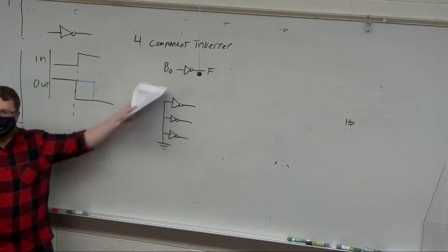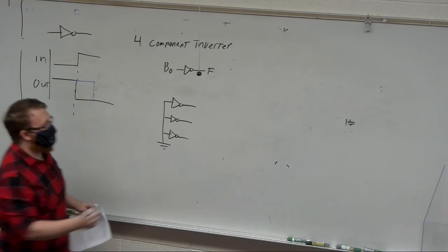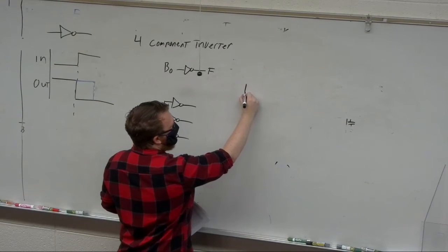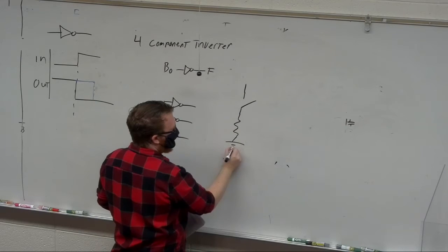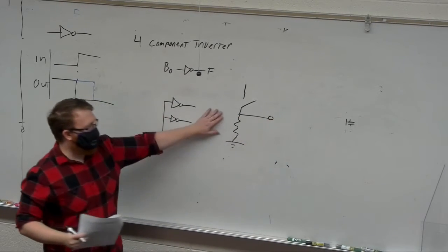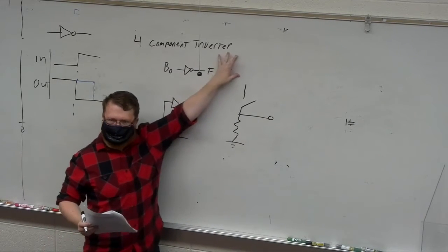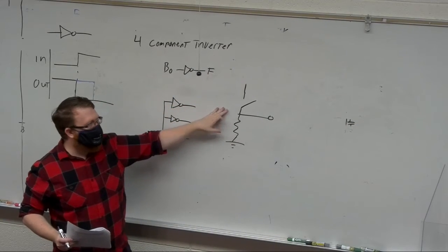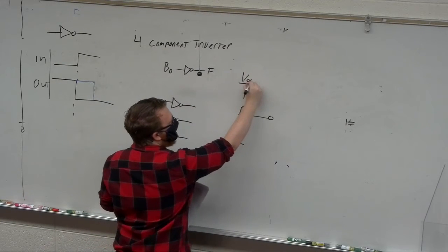But if these are floated at the input, some of you discovered this, right? You design circuits in the lab. So the ideal situation is we have like a switch, a resistor, and this is your output. But some of you didn't use this, what we call the pull down resistor, right? If you put it up here, it's the pull up resistor. You switch the order of that. If you don't use that pull down resistor, we know that it is, so let's break that connection and explicitly write VCC.